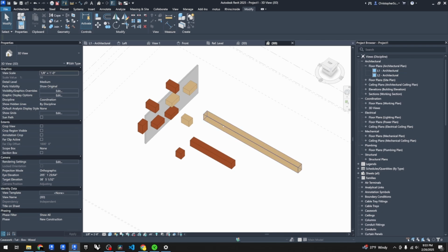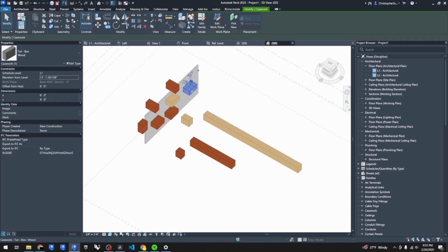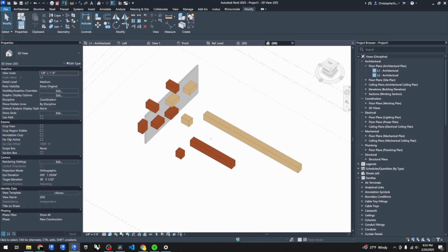And so to do that, by making each of these their own family that I can then select, if we look, we only have a single base family for all of these different versions. And then we have a couple of different separate types. So we have 2 different types here. This is going to help Revit's performance. Don't discredit the workflow to make your own family. Even though it might be something simple, it could help you immensely down the road.